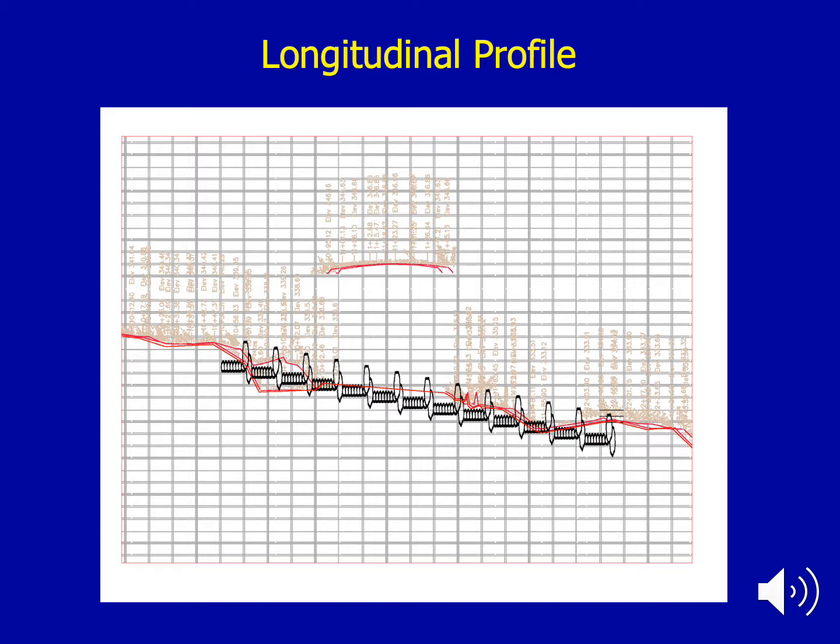This was presented to me with another solution, and the question was, what's your opinion? Which one do you like? Do you like the rock weirs? Do you like the roughened channels? I am totally missing geomorphic context here. I do not really have the slope of the design, and I don't know what's happening downstream. I don't know what the channel slope is here. I don't know what's happening upstream, if I'm looking at aggradation or maybe incision up here. Again, no slope. Really hard for me to weigh in on what works here.